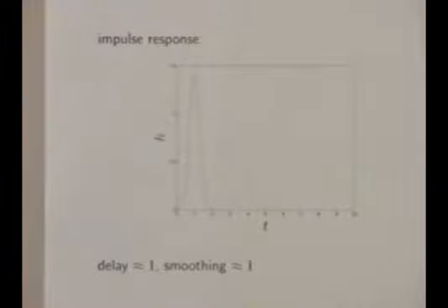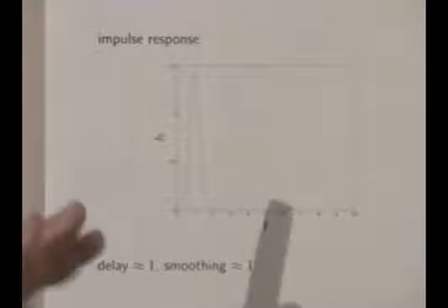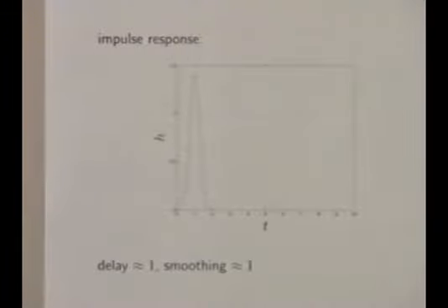Now, if an impulse response is a delta function at t equals 1, what is the system? It's a delay is what it is, because it says that the output is precisely what the input was 1 second ago. So again, these are just various ways to look at this and get a good intuitive feel for what it does. I guess if you can just look at integrals and formulas and understand this, that's great.